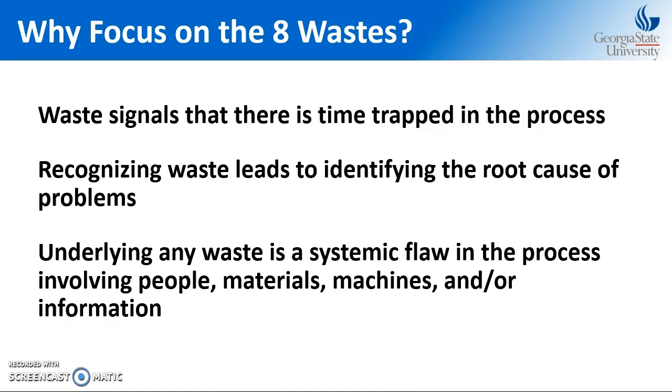When we recognize waste, that helps us identify the root cause of a problem. When we see that there's rework needed, that means something's not being done right along the way. When we see that there is excess inventory being created, that means either our forecasting methods are not good, or we have a system where we could make it better by making it more of a pull method, where we are only replacing things or building when there is an order, when there is acknowledged demand from the customer. Every waste represents an underlying flaw in the way we've designed our process. And that's why we should focus on these 8 wastes.